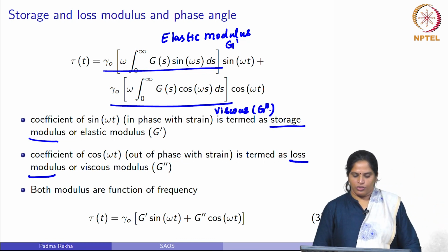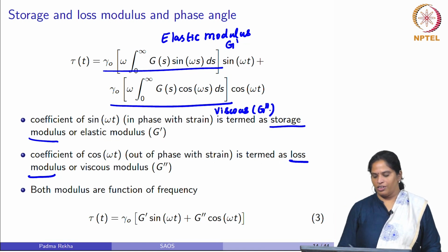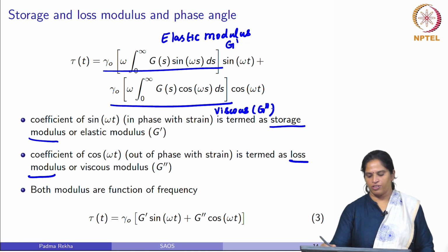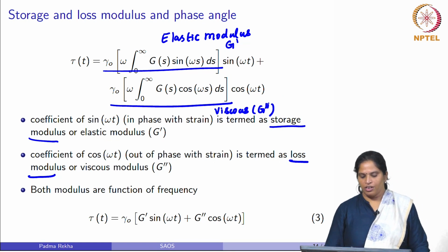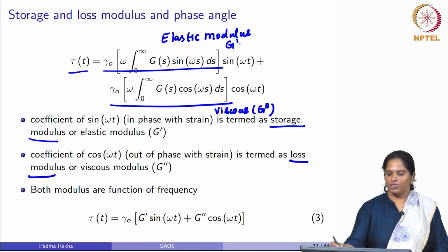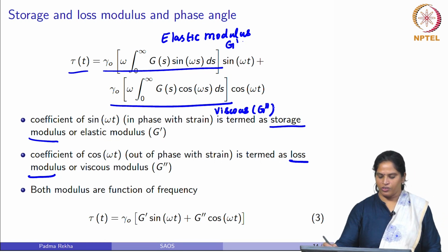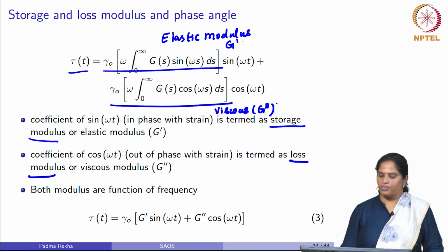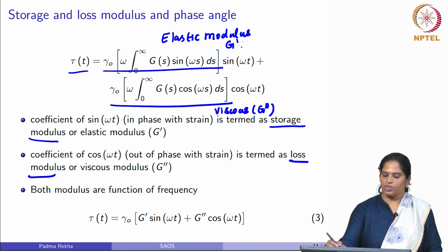So, you have two functions here: one is the in phase component, the storage modulus, and the other the out of phase component, the loss modulus. If you want to find the stress, you need the two functions, the storage modulus component and the loss modulus component. You can also see that these modulus functions are frequency dependent.